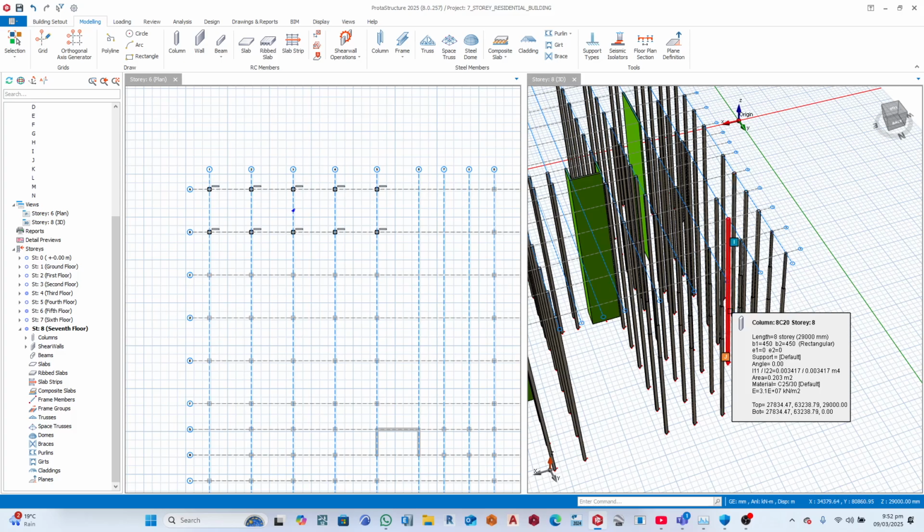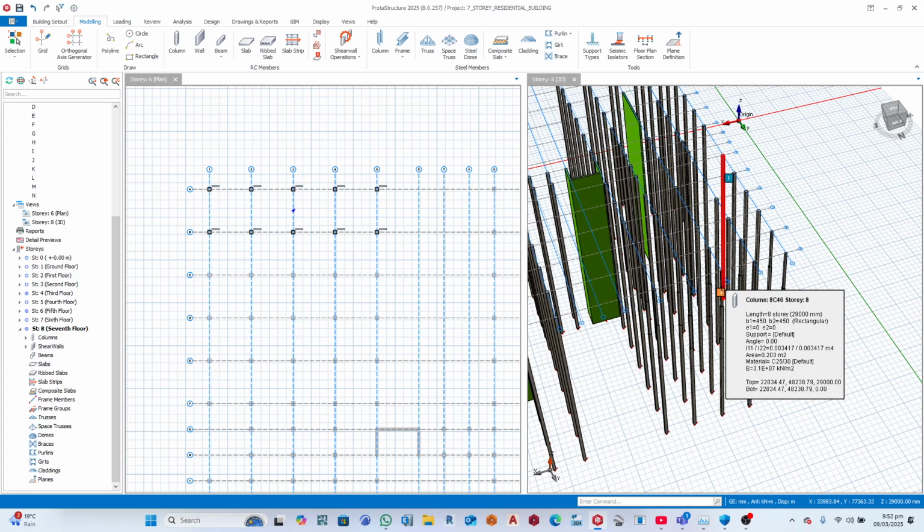Yes. So that loading will move in form of stress through the reinforcement. If it's being transmitted from the reinforcement above, that's why when we lap like that, the stresses, it's axial, so it's coming down from the top. So the stresses are transmitted from the top reinforcement into the bottom reinforcement, and they go down like that.